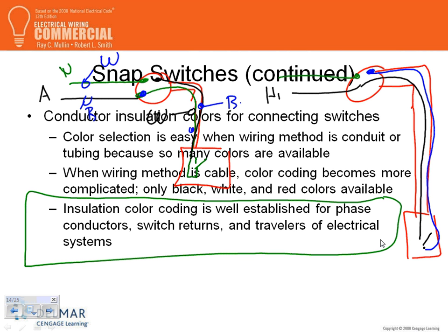Very important, but that's 2011. Very good point. But you have to know that, guys, because you're going to be designing this. What I showed right now would almost become obsolete, re-identifying them. Not obsolete, almost. I'm going to say almost because there are other scenarios, because you need a neutral on the ground in the switch right now. How do you bring a neutral to the switch? I bring a 3-conductor cable instead of a 2-conductor cable. This is a money-saving process.